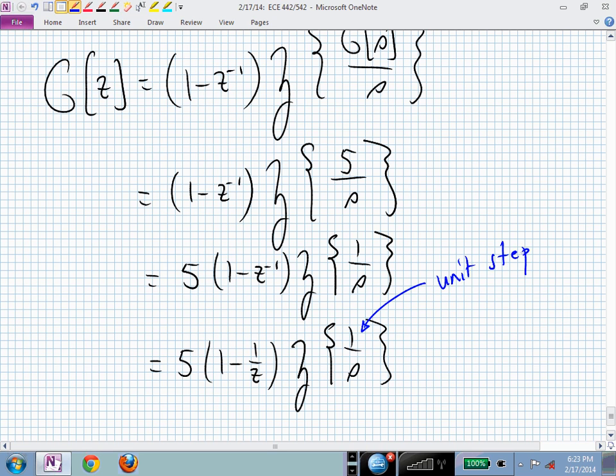And remember what we're doing inside this Z curly brackets? We're inverse Laplace transforming whatever it is, 1 over S. That's now just a line or a constant 1. We sample it, and now we Z transform that sampled sequence of numbers. And what happened when we sampled a unit step in the discrete time setting? Do you remember what the transform of that was?